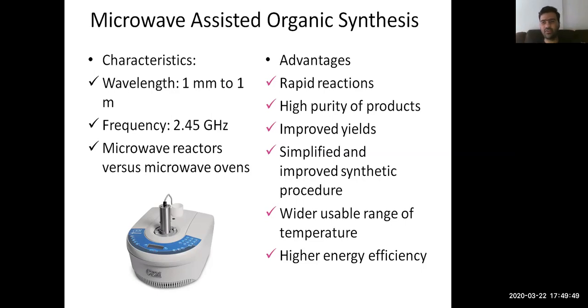It's just that the microwave radiations are coming out. They go and strike individual walls and they get quenched. So they offer certain places where there is intense microwave that is observed, certain places where the microwave radiations don't even penetrate. That is the reason why you need a turntable. The turntable is then going to help you in achieving heating of all the parts. So you tend to rotate the food material or the container in which you've placed your article, and as it rotates, it keeps absorbing microwave radiations, right?